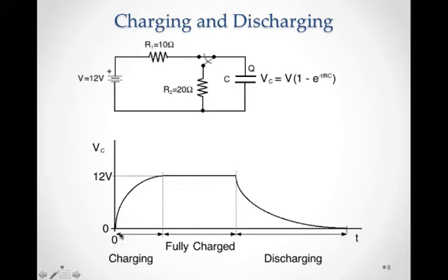And so as time goes by here, the capacitor will charge up more and more and more, and it'll increase at a decreasing rate, and that's what this shows, until it finally, where this will finally get close to 0, and our capacitor here will be the same voltage as our power supply voltage of 12 volts. And so it'll charge up until it's fully charged at 12 volts here. And as long as we have the switch connected up here, it'll stay fully charged.